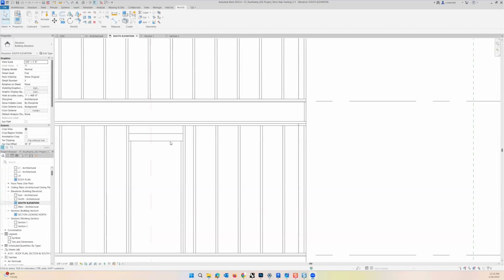Okay, so as I mentioned, it's 6 feet 10 and 7/8 to level 1 for the header. I have a 3 foot 6 inch high rough opening, and what I want to try to do is make a copy of this and position it in place and then stretch it so that it's just going between these trimmers.